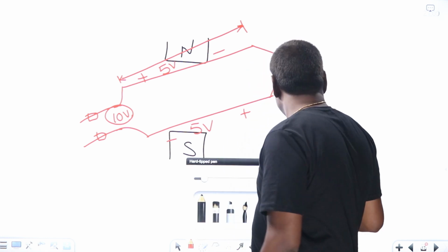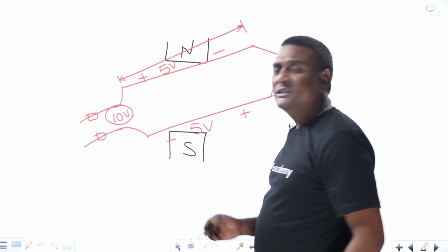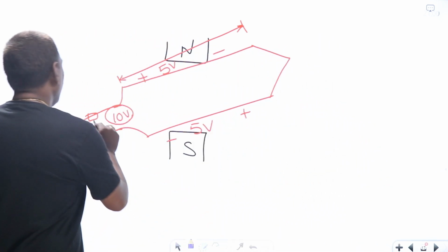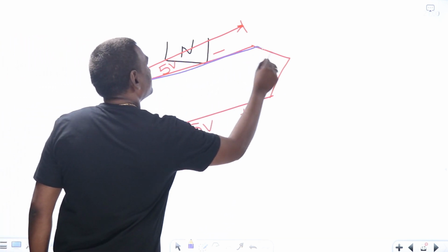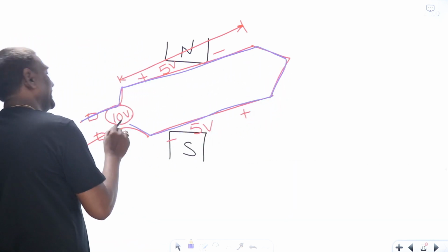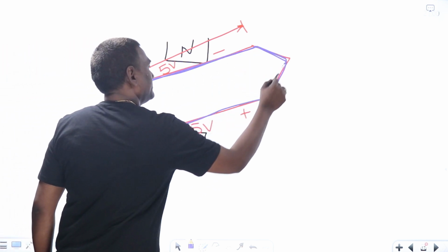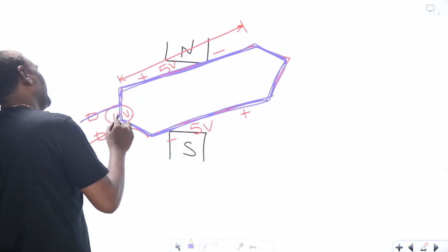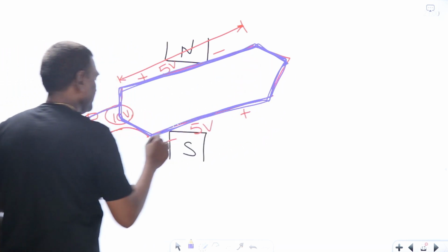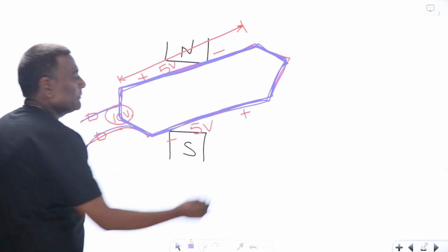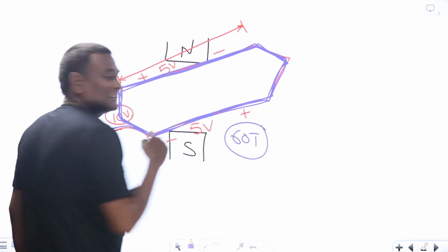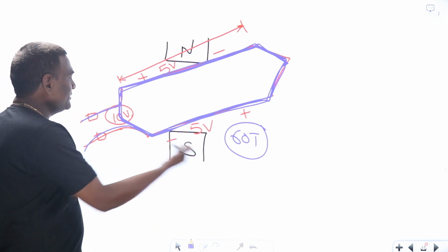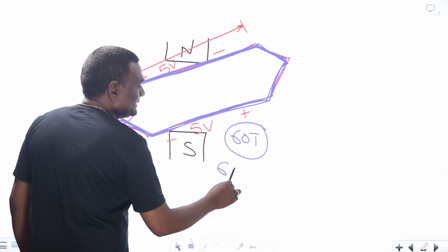For 600 volts, let me have a back-to-back connection, again back-to-back connection, again back-to-back connection. In that way, if I maintain 60 turns, how many terminals are going to come out? Only 2, with 2 brushes, meaning 60 turns into 10 volts is directly going to be 600 volts.